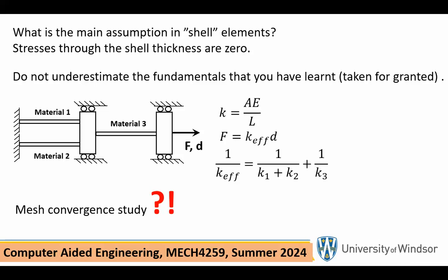Now, in the setup of doing a finite element calculation on the test or on quiz, etc., I'm not asking you to do that, but that's always in the background. If you're being paid to do finite elements down the road, hopefully some of you will, or if you're doing this for your project or your research, do not forget that one run, tear it up, throw it in garbage. Okay, you really have to do mesh convergence study, and this is all based on the assumption that your initial modeling of the problem was okay.